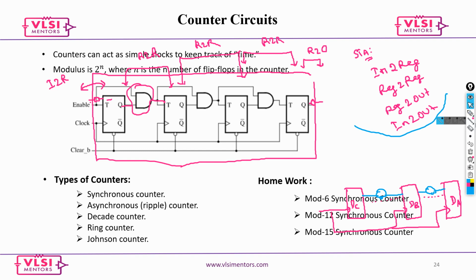Any questions? So that is why you don't need to worry about whether it is a counter or shift registers and all. What matters to you is how many logic cells I have here and how they are placed. Is there too much distance? What is the cell delay and what is the net delay? What is the overall delay? That is what we actually bother about.